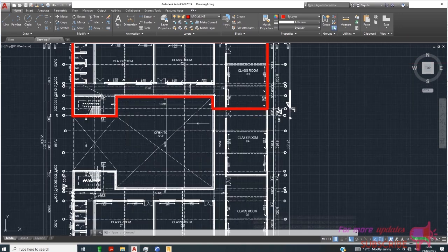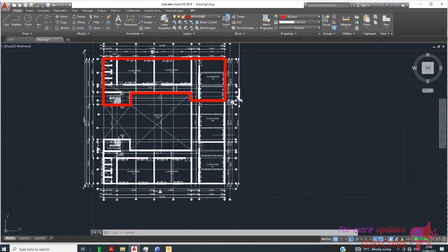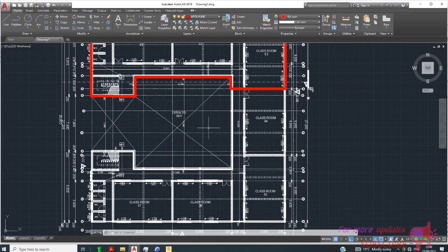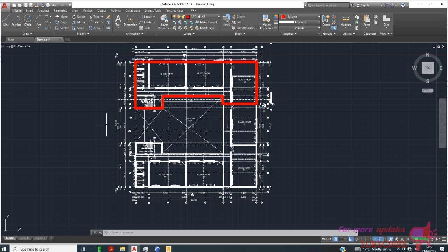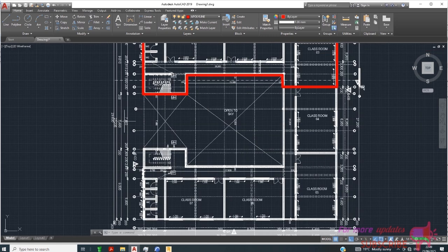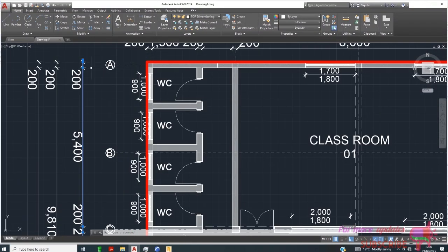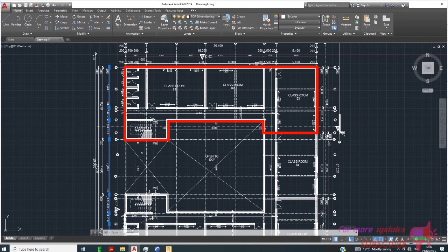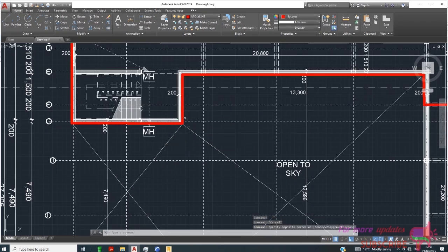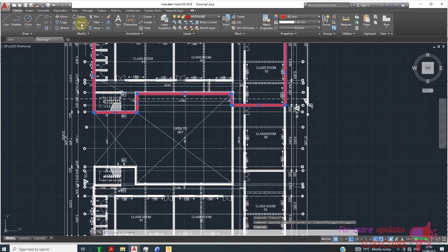I can do this exact same. I can get the exact same shape on this side below, because if you check, I can even just mirror this polyline about. I'm not sure this one is the same line. Okay, I can just mirror about this one. If I select this polyline, let me select, and then I want to mirror about that midpoint. Okay, and then that way.